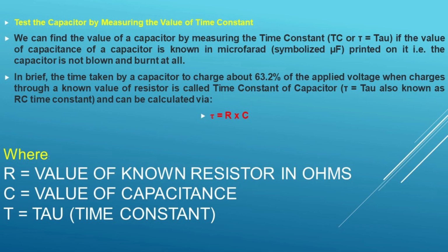Note that the reading may be less than the actual value of the capacitor, the rated value, due to the tolerance of plus or minus 10 or plus or minus 20 percent. If you read a significantly lower capacitance or none at all, then the capacitor is dead and you should change it with a new one for proper operation.